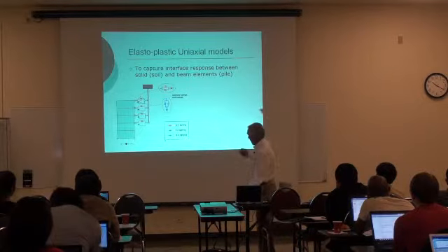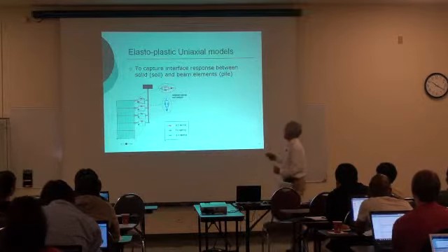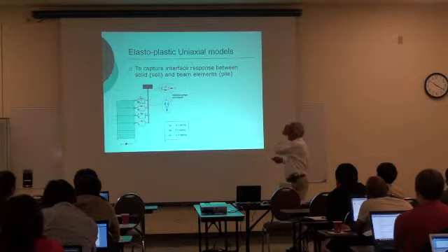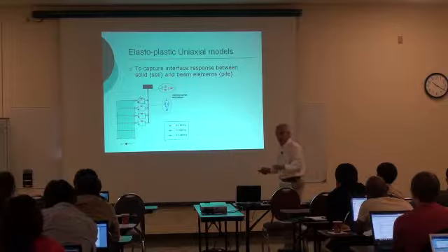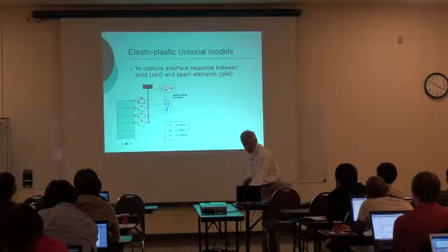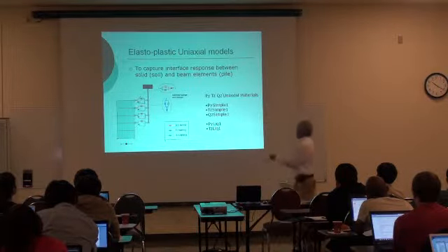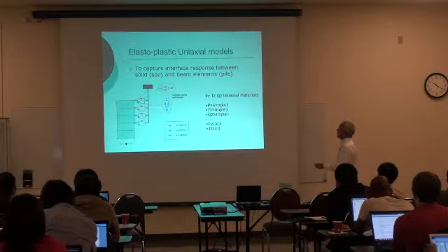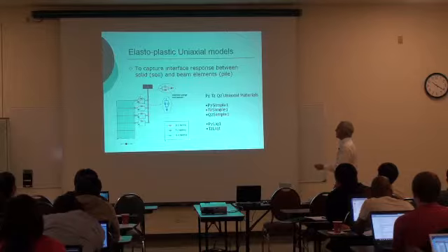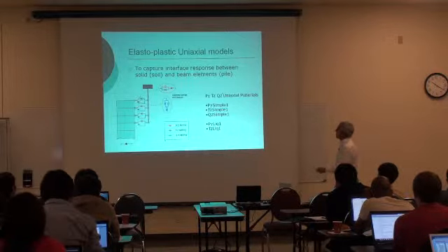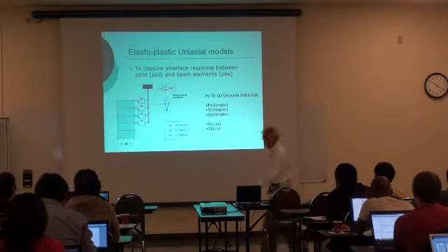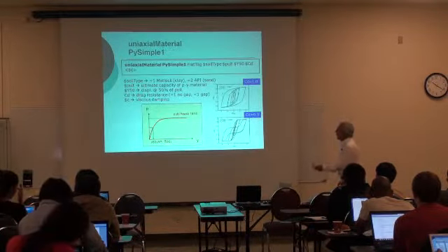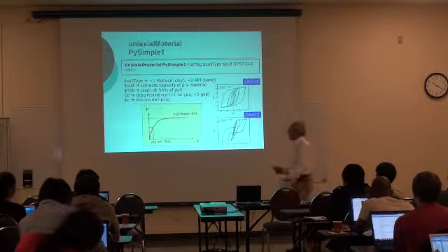So what was done here in OpenSees is to implement uniaxial materials that capture that experimental response pretty well. So we have what is called the PY simple material, the TC simple material, the QC simple, and then there are some materials that are also used for the soil when it liquefies. For example, this is the type of PY behavior that you want to capture.